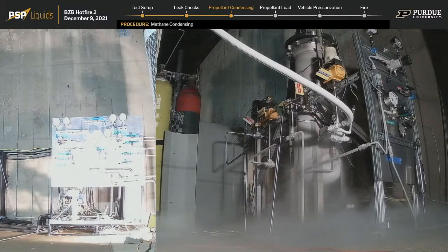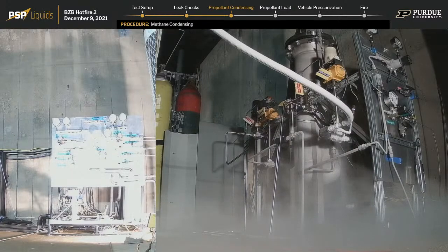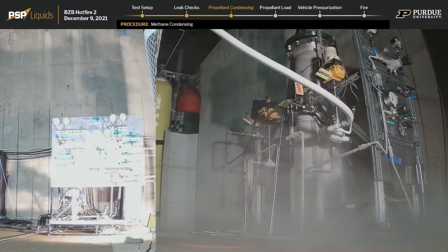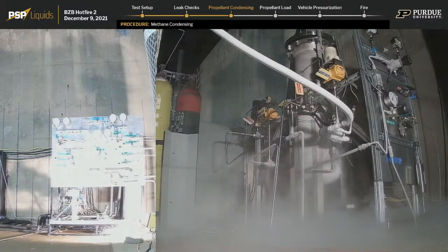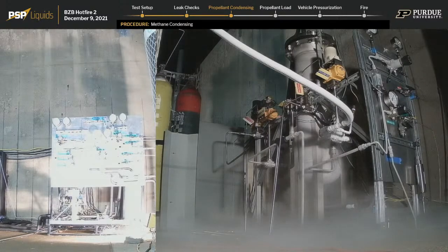So, can you talk about why we decided to go with a pressure system instead of maybe an autogenous recovery or turbo pumps or something of that nature? Yeah, so similar to what we did with our ignition system, one of the main reasons we went with a pressure-fed system is that it is a very simple way of making a liquid rocket. It's very simple and it's very cheap. It really cuts down development time. Pumps are very difficult to design and operate. It would require a huge testing and validation campaign. And really, our aim here is to get the minimum viable product that can accomplish the mission, which we can do with a pressure-fed system.